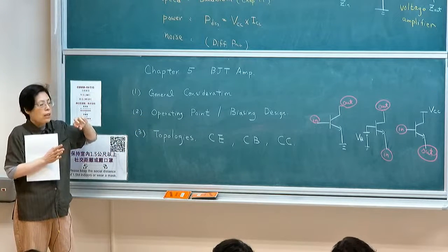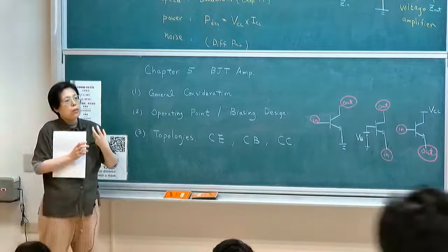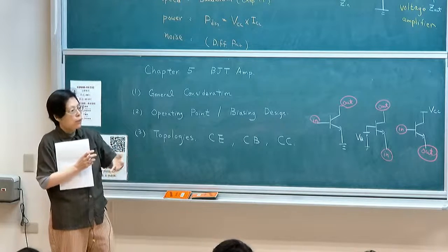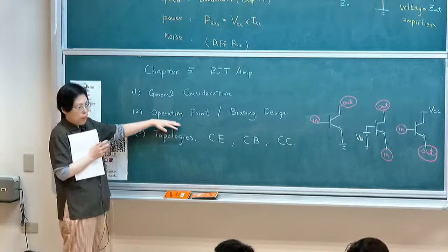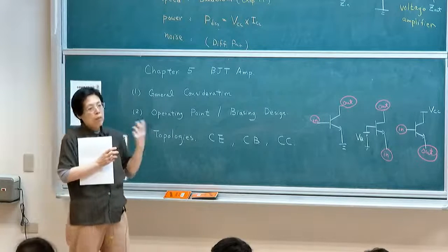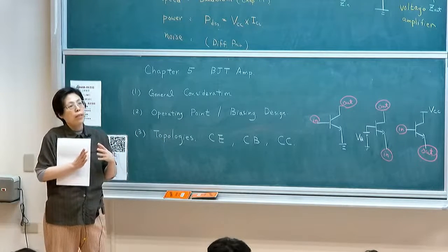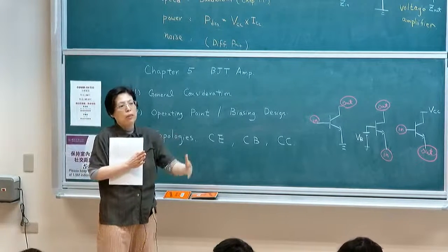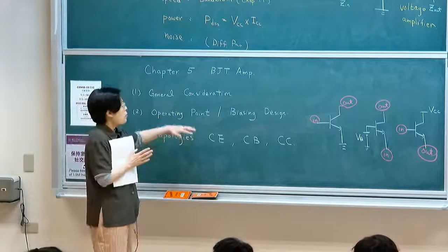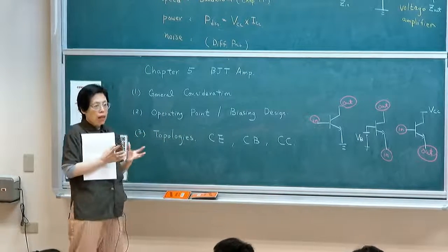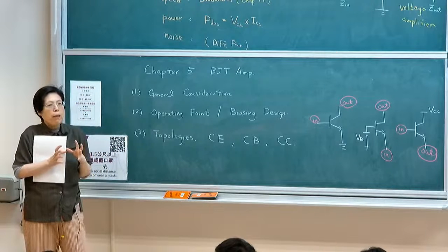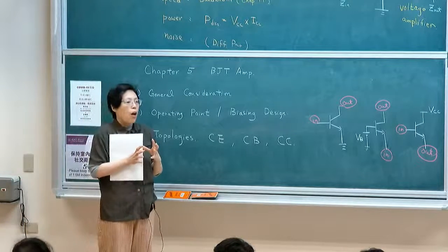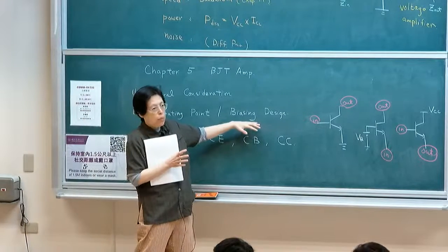As I said, when we want to start with generating a small signal model, you start with understanding where your standing point is. That's called the operating point. Some of the examples are where the operating point is given to you. For example, I'm telling you the biasing current of the circuit is at a particular point. But in a lot of designs, one of the key challenges for the designer is to place your circuit at this particular operating point. That's called the biasing design or biasing circuits.